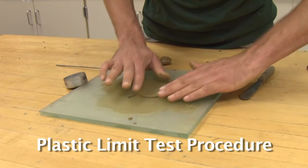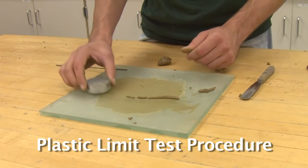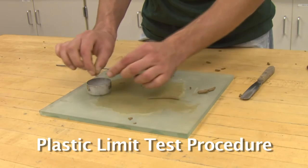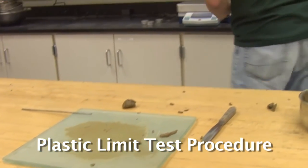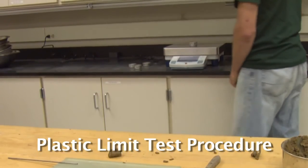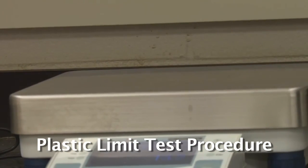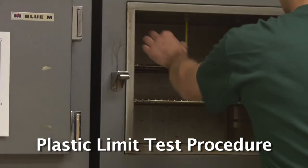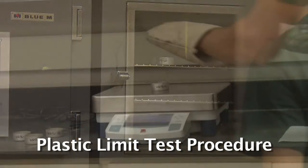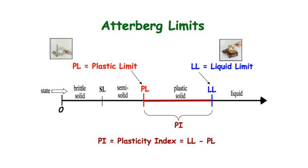Once the soil crumbles at 3 millimeters, collect samples of the crumbling soil and place them in pre-weighed tare cans for moisture content determination. Repeat the test enough times so that enough soil has been obtained for 2 moisture content samples of approximately 6 grams each. Record the wet weights of the moisture content samples and place in the oven. Reweigh the samples again in 24 hours. The average of the 2 moisture contents is the plastic limit.